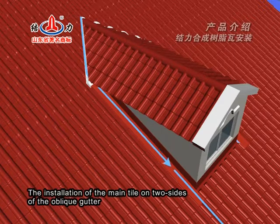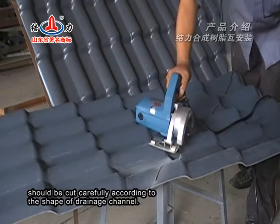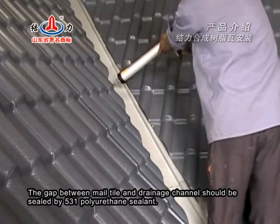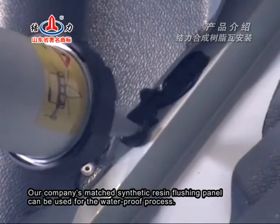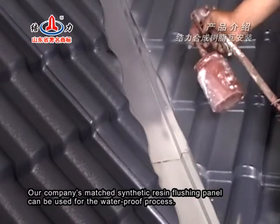The main tile on two sides of the oblique gutter should be cut carefully according to the shape of the drainage channel. The gap between male tile and drainage channel should be sealed by 531 polyurethane sealant. Irregular places should be repaired. Painting at last. Our company's matched synthetic resin flushing panel can be used for the waterproof process.